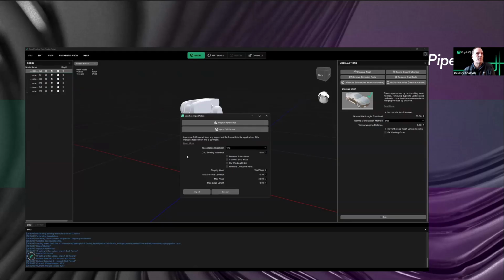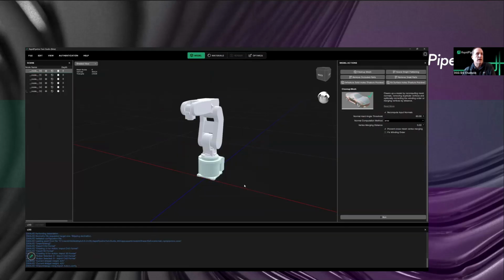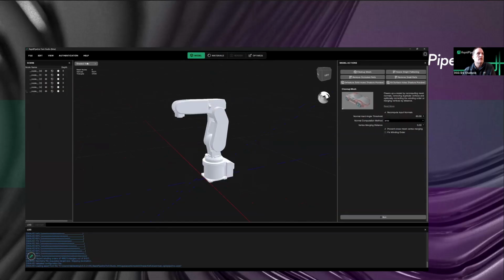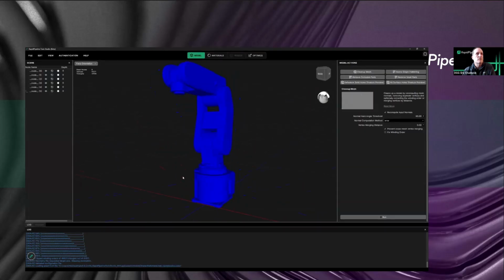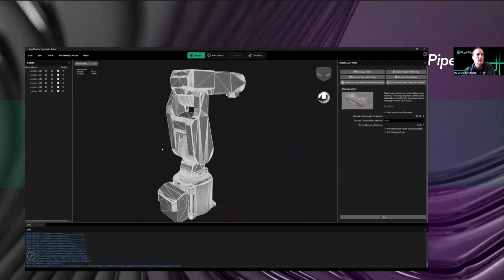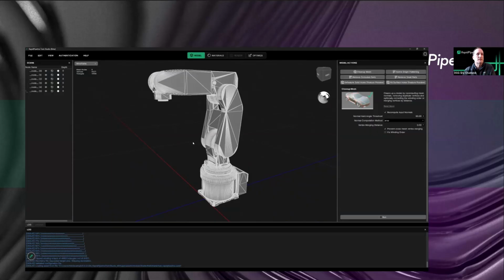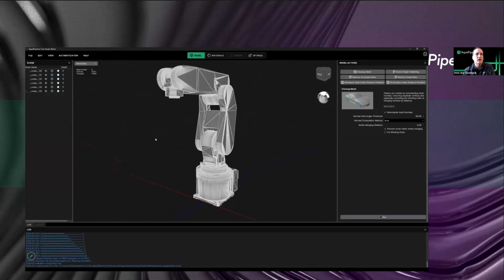So robot, open, and this time I'm going to fix winding order on input. And let's go extra fine. What the heck? Why not? And just leave it at that. So now when it imports, it'll do extra fine tessellation. And it's done. And if we look at face orientation, it's all facing the right way. And it just does it automatically, right? It does it not on a per triangle basis, but across whole elements of the model, all the connected vertices. So it won't do it per triangle and mess things up and have some things be inside out and others not.